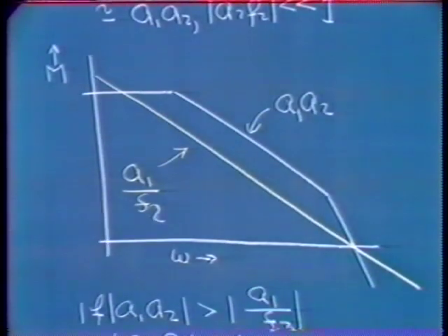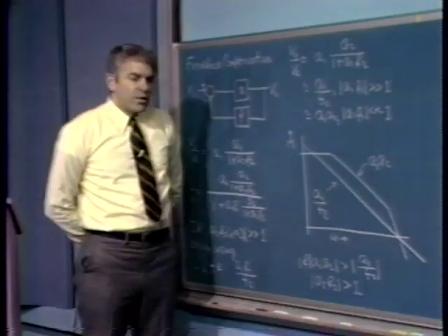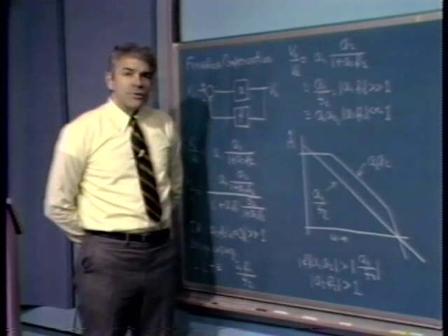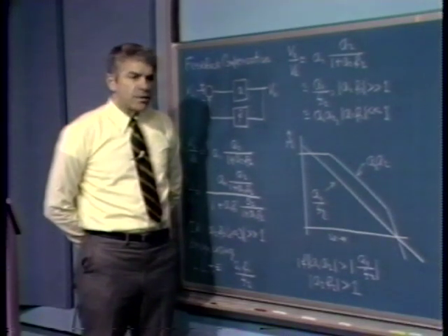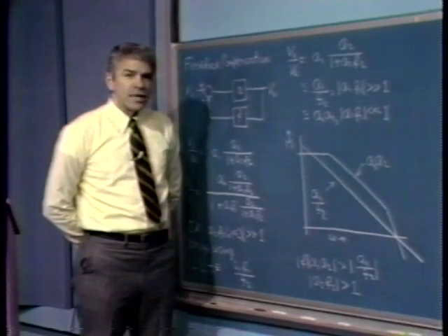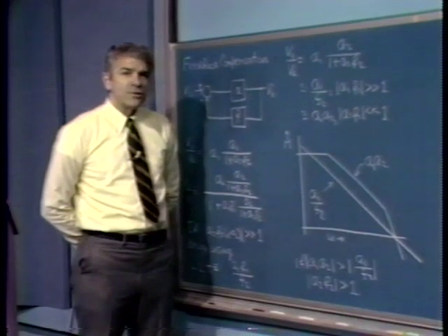We find that the transfer function of the feedback element in the minor loop very frequently is a 0 at the origin. We'll see an example of that in the next lecture when we do an example of this kind of compensation using an operational amplifier.